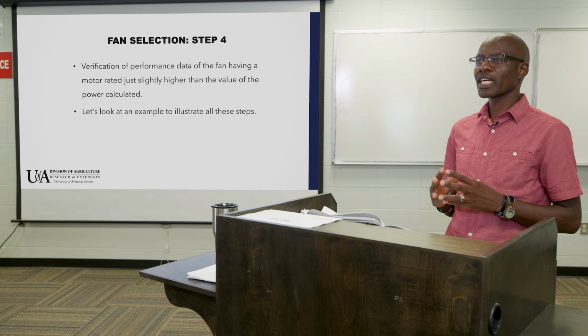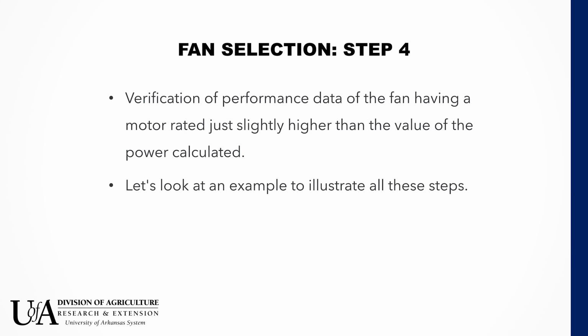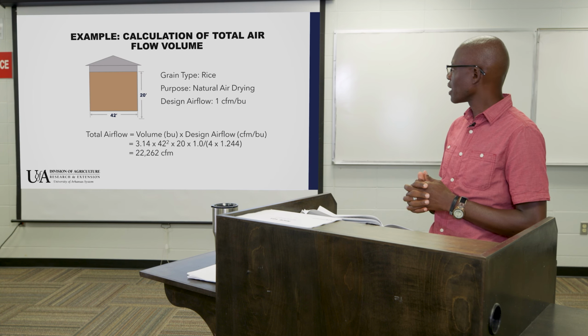Once we have calculated the power that we require, the next step is to verify the performance data of that fan and select a fan that is performing at slightly higher power compared to what we calculated. So to be able to understand some of these steps, let's go through an example that helps us put all this together.